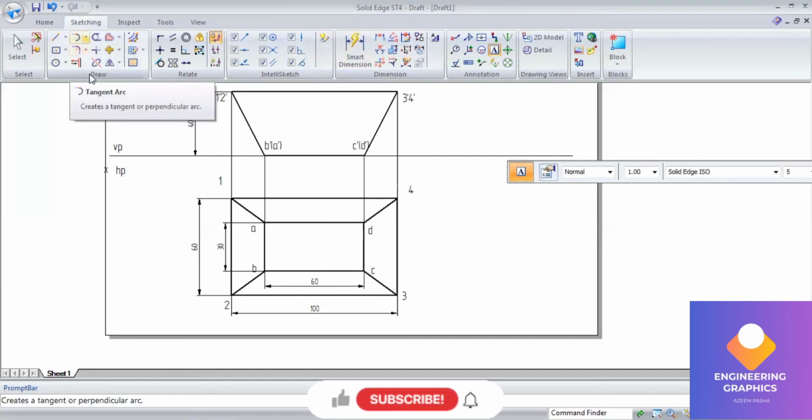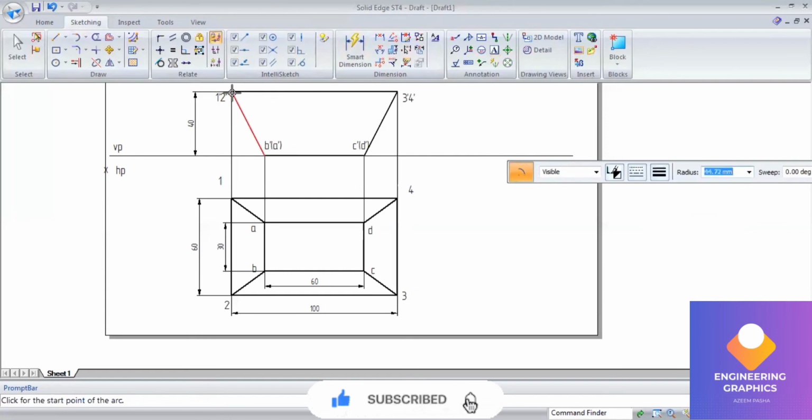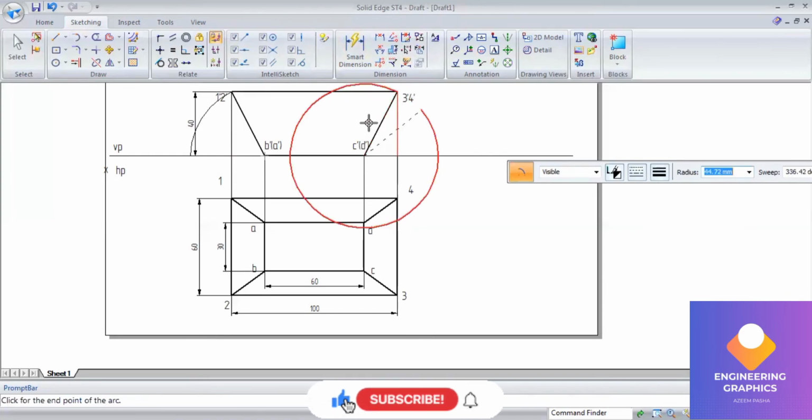Now we have to draw the development for this. I'll go to arc by center. Measuring from this end, this length I'm going to measure and cut an arc till the XY line. The same way I'm going to do it on the other side also, from C dash to D dash, C dash D dash to 3 4, measuring this length from here to here, and I can cut the arc.